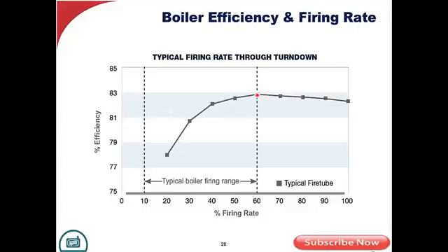So you've got to find out from that manufacturer, from that sales engineer, if I put this boiler in, where is it most efficient? So I can size my load accordingly and keep it there as much as I possibly can.